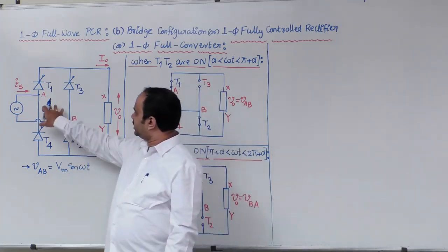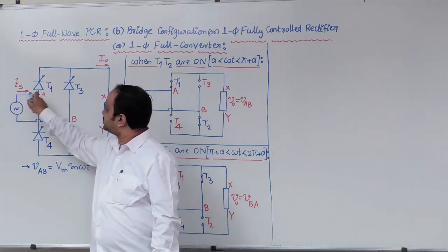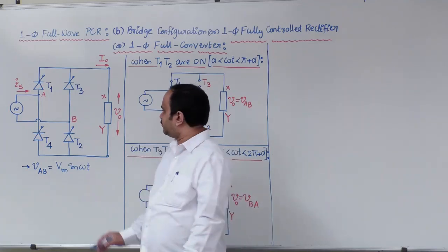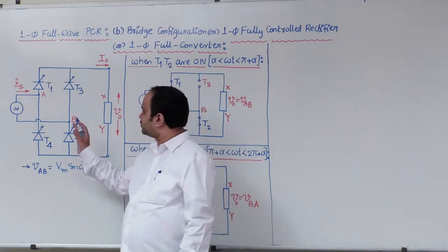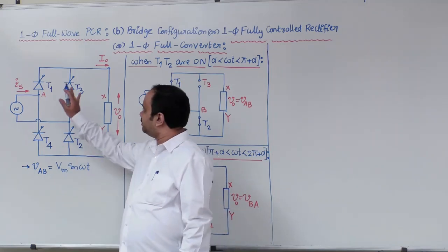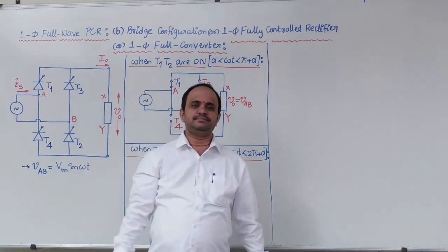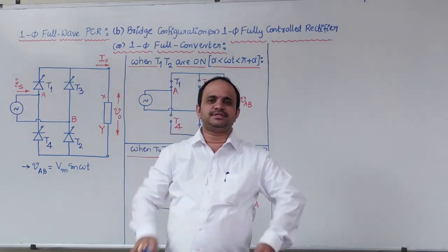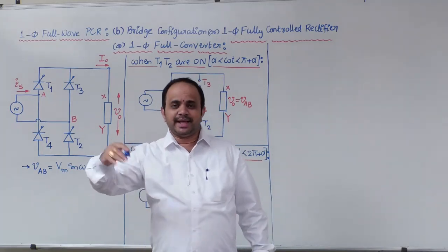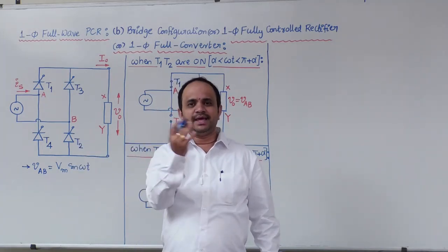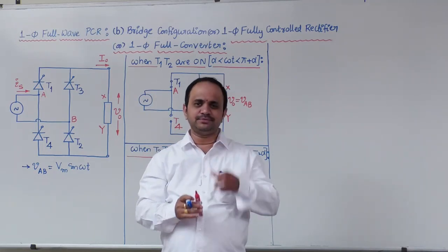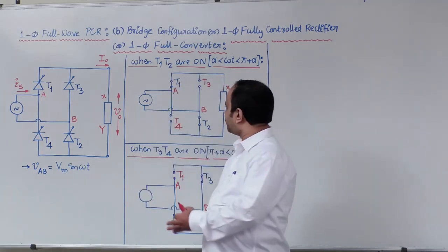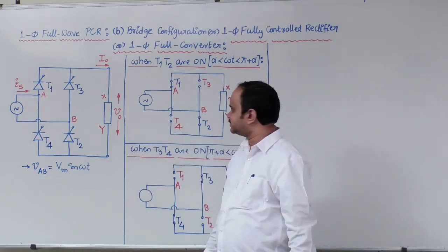If you remember, while starting this circuit diagram, I just showed this reference direction for Is. The reason is, follow carefully. The good practice for network analysis is, in the beginning, it is preferable to give some directions of reference for currents and polarities of reference for voltages. During the analysis stage, if you get the same as the reference, treat them as positive. Opposite to the reference, treat them as negative. We'll follow the same thing here. That is a very basic notation.